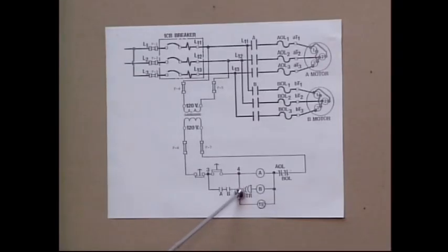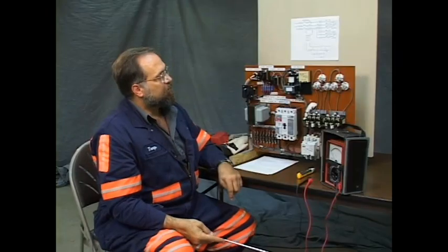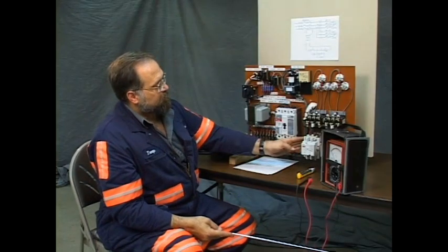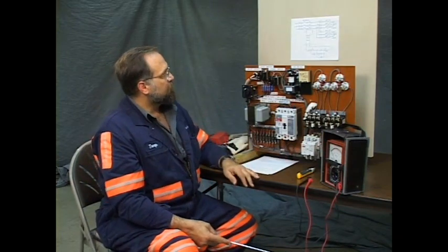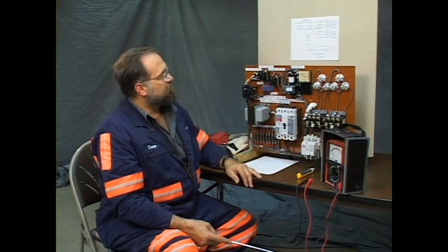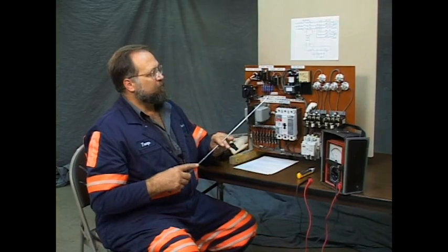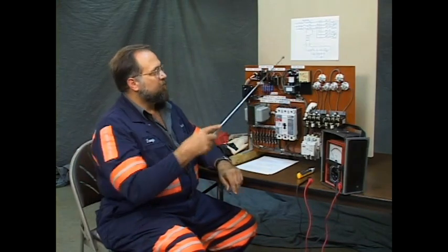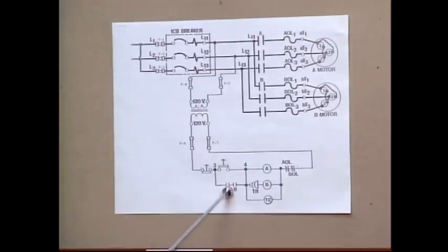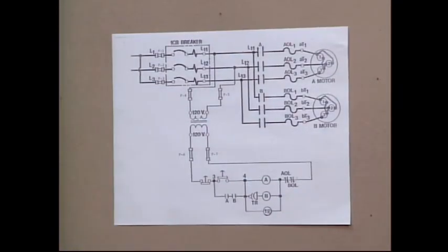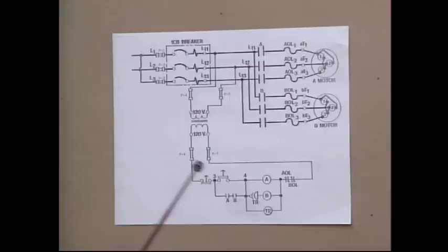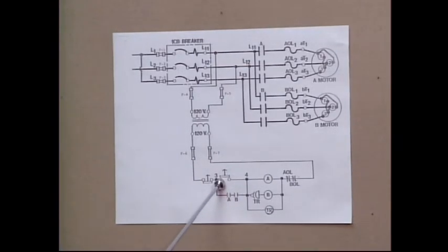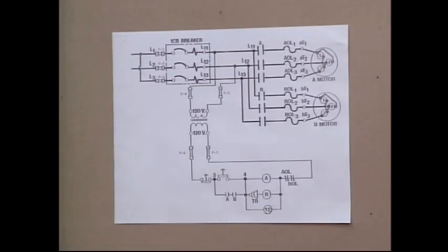When you release it, the circuit should be maintained through the holding circuit, through the A and B interlocks, the auxiliaries that we just checked a few minutes ago. They should maintain the circuit. But with it not started, you have an open switch here and you have an open switch here. Nothing should happen. But on our problem, as soon as it's energized, without the start switch being depressed, it takes off, it goes.